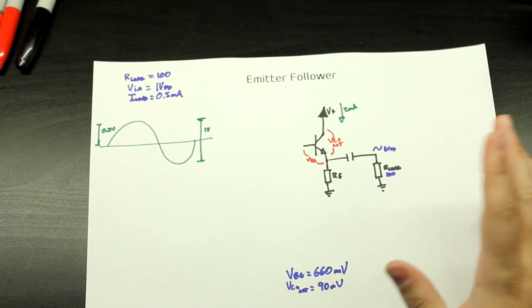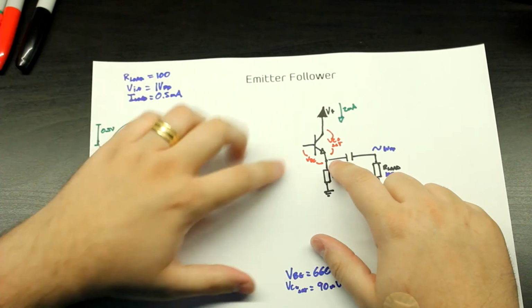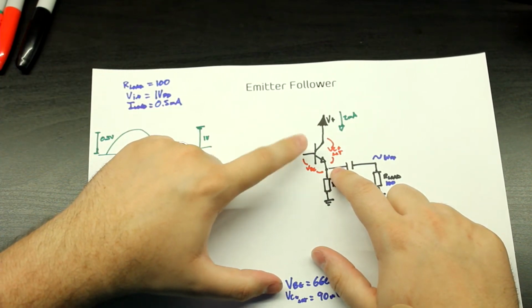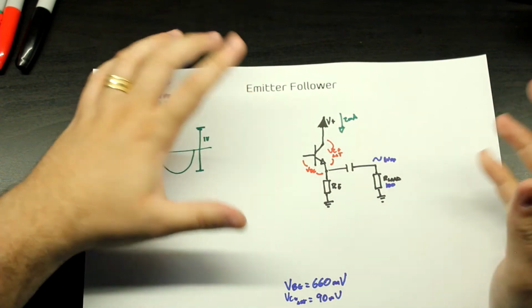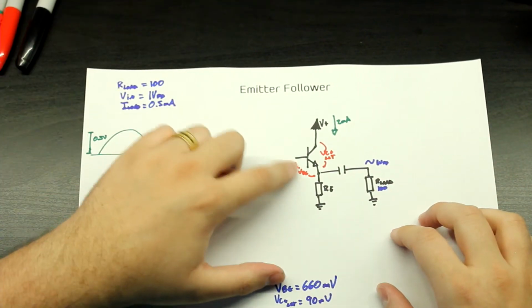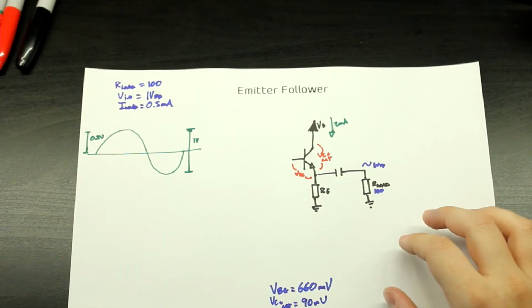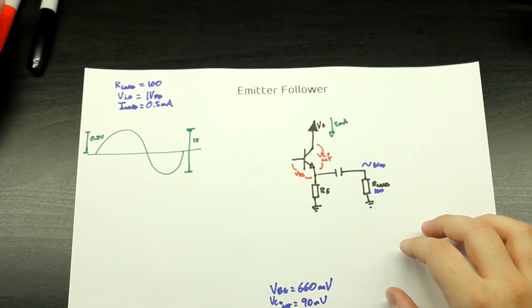So you need a voltage that's greater than 0.5 volts here, which means here we are probably going to have something greater than 1.2 volts. Because then we get the diode drop here, and then up here appears only 0.6. So let's think about that.